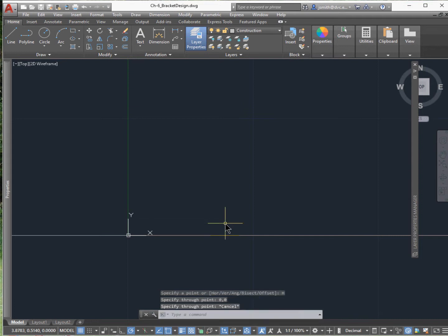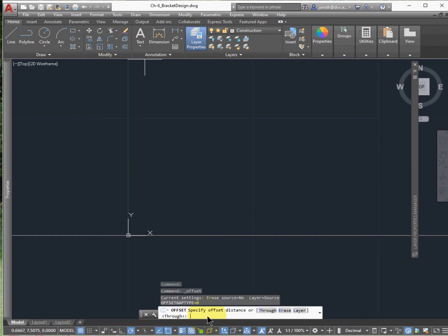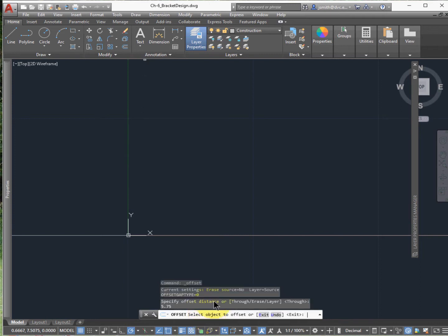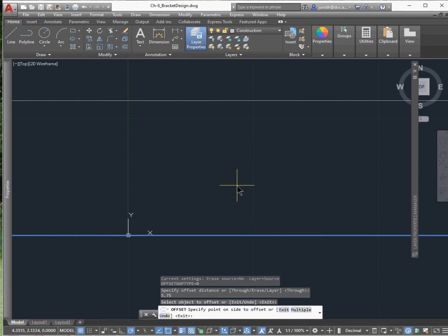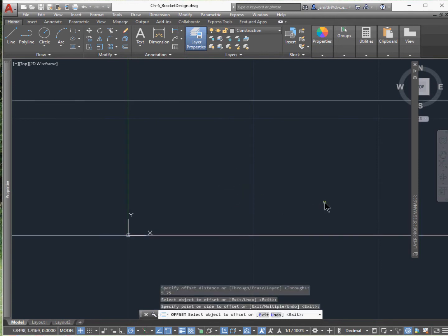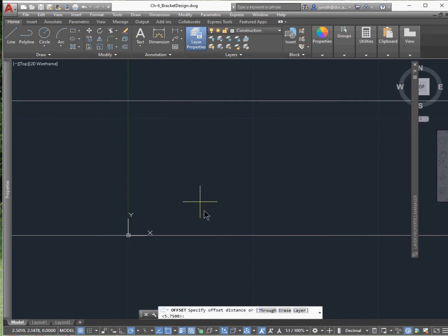And now what I'm going to do is rather than make new ones, I'm just going to offset this based on my drawing. And so you basically have to key in what you want. And so this first one, you can see is 5.75 inches. And that's actually the height of the part that I'm making. And you can verify this. I'm going to verify all the dimensions after I make this, or part of the way through here.